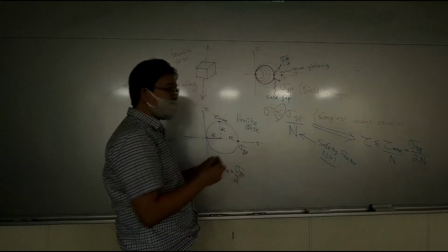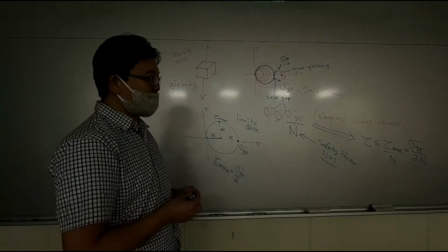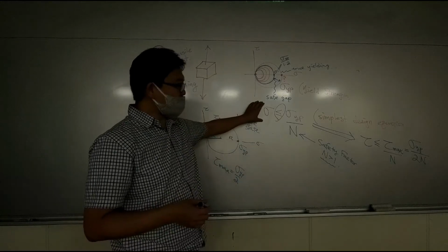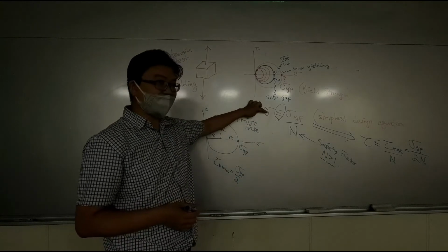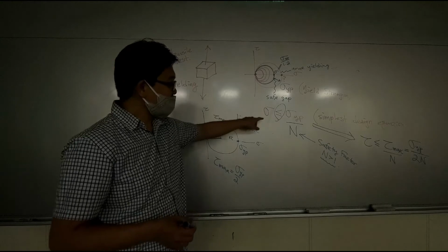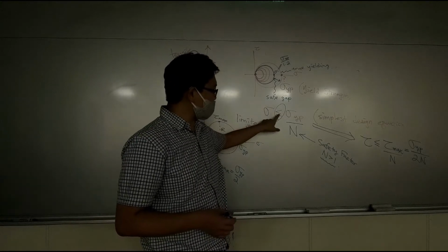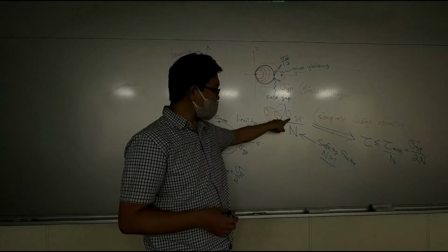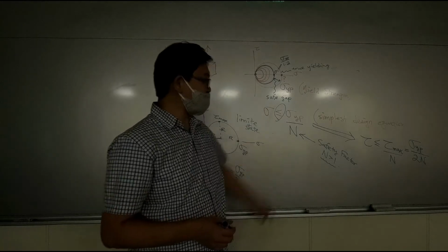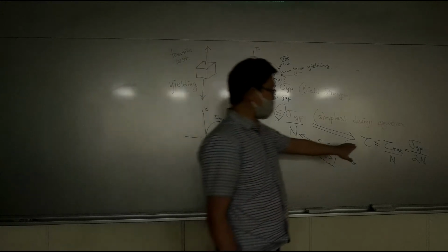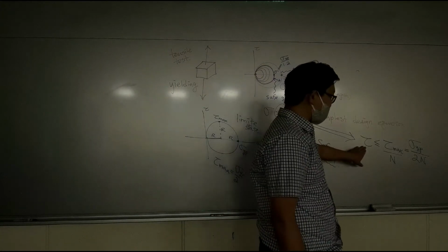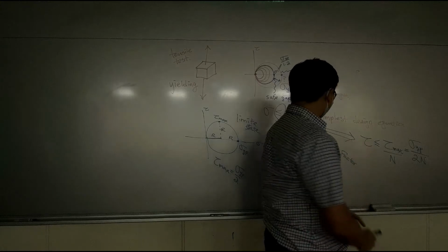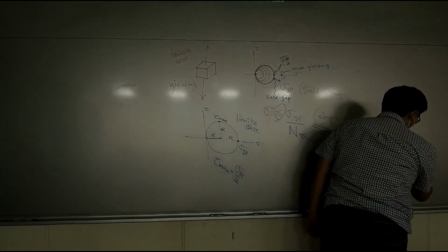So it's a totally different way to analyze this. If I want to focus on the normal stress we are facing, then the normal stress cannot be larger than your yielding strength over a safety factor. But if this time I'm focusing on the shearing stress, then in this case, you have a 2 right here.